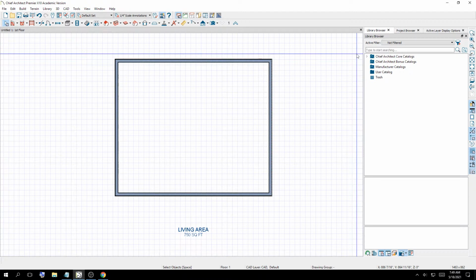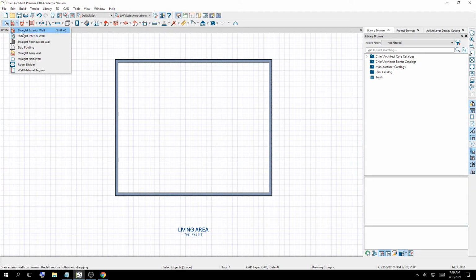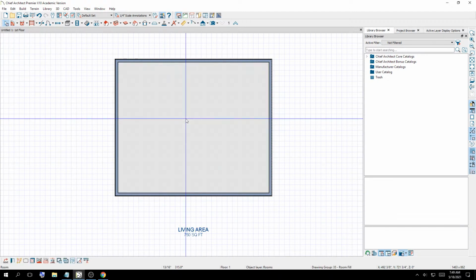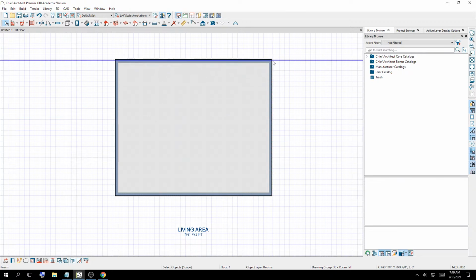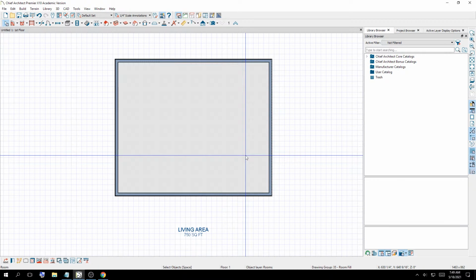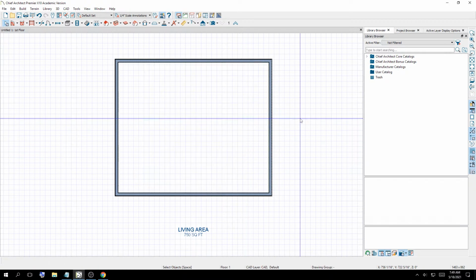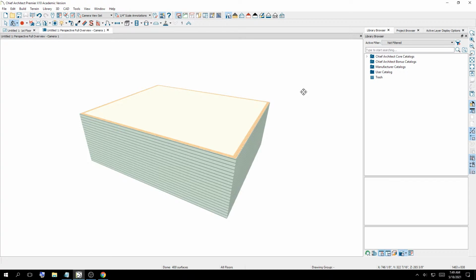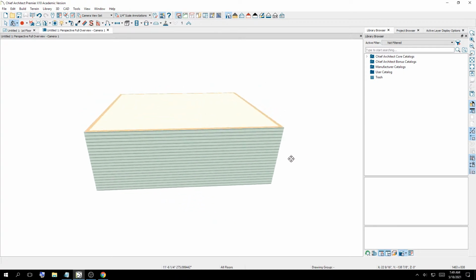So we have an enclosed perimeter using a straight exterior wall. We have 750 square feet auto-calculated. If I click on the inside, you can see that I can actually select that interior area. And that's because, once again, the 4 walls have snapped and are connected together. If I hold Shift on the keyboard and press K, Shift K should give us a 3-dimensional view of what we created. Now these are default settings. These are default textures. We have this teal green color I'm personally not fond of, but that's irrelevant at this point.